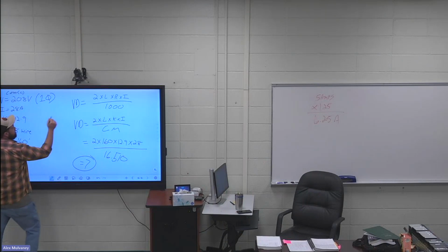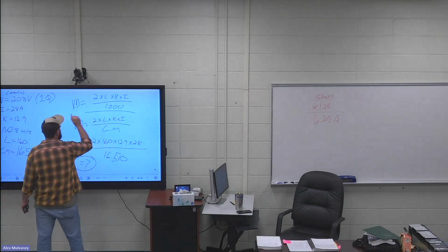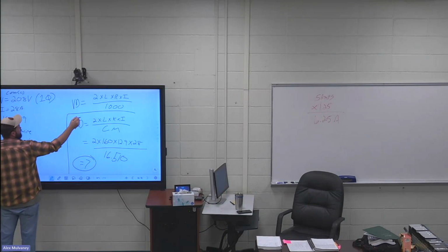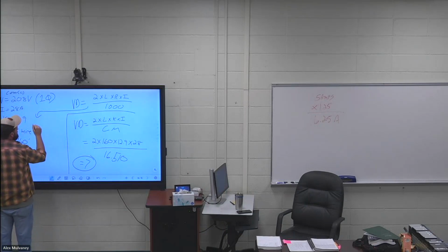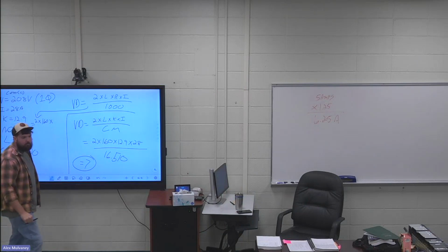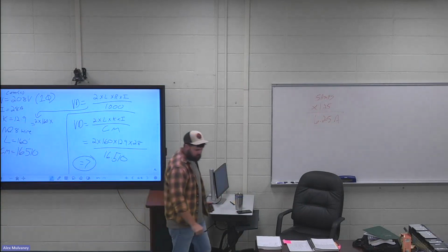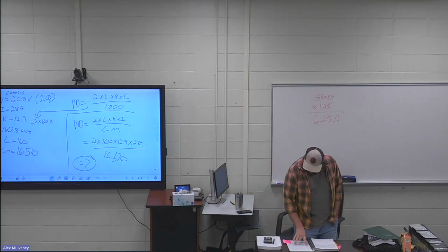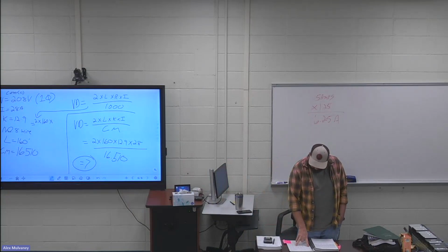All right, doing my other voltage drop equation right here. I know I'm not the neatest. I'm going to say this is separate. So we're going to use that one. So 2 with my length, 160, times R. Do I have R? Nope. Can I find R? Yeah. Where? Chapter 9, Table 8. So what size is my wire? 8. Everybody see 8 in that table?